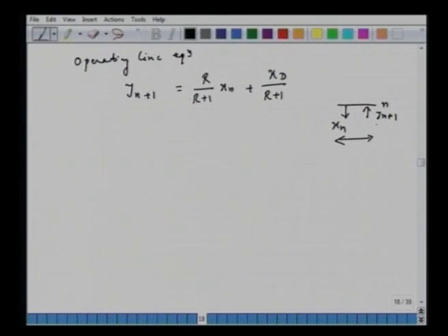It connects yn+1 and xn by this equation, which was obtained, if you recall, by taking this envelope, region 1, around this condenser and this nth plate to have this material balance here.